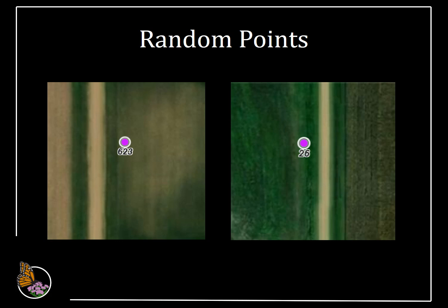If you are selecting a random right-of-way point from the IMMP mapping application, you will notice that the random sampling points usually don't fall exactly where you will start your monitoring plot. Your starting point should be the spot closest to the point where the road and vegetation meet. To find your starting point, navigate to the random sampling point provided, shown in purple, and then walk to the place closest to this point where the road and the vegetation meet.